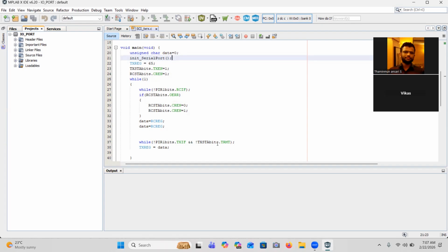As far as this microcontroller is concerned, in which we are working, that will redirect the program counter value to program memory address 4. In program memory address 4, we should have a branching statement to the address where we have an interrupt service routine.